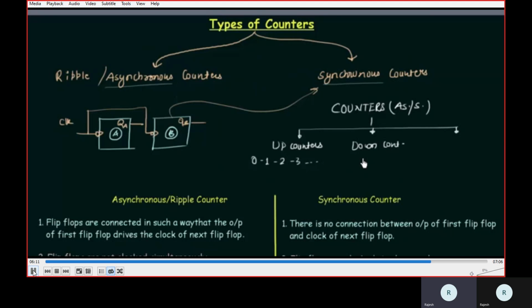The transition of Q to Qn plus 1 will give the corresponding inputs. Write down those inputs, and for which input values are 1, take those minterms, do a K-map, and generate the hardware to be connected to the inputs of the flip-flops. So this covers the topic of counters.